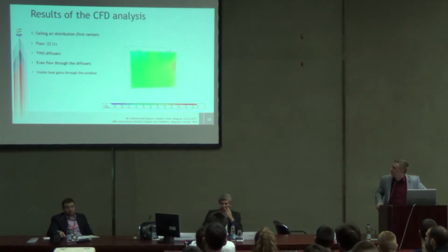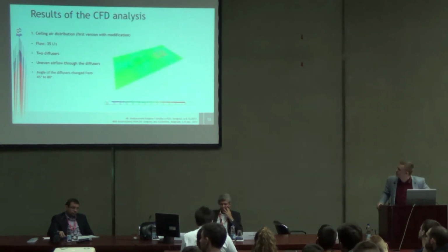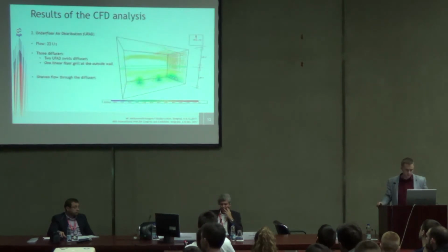But as the temperature of the windows and the outside wall is pretty high, we can see the heat gains entering the room. So with raising the airflow and changing the diffuser angles, I got better results. And that's the same situation, but from another angle.